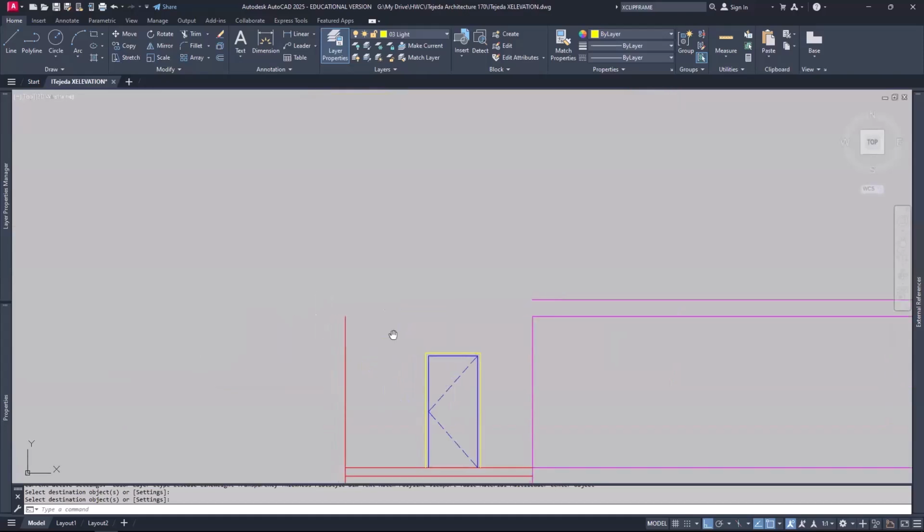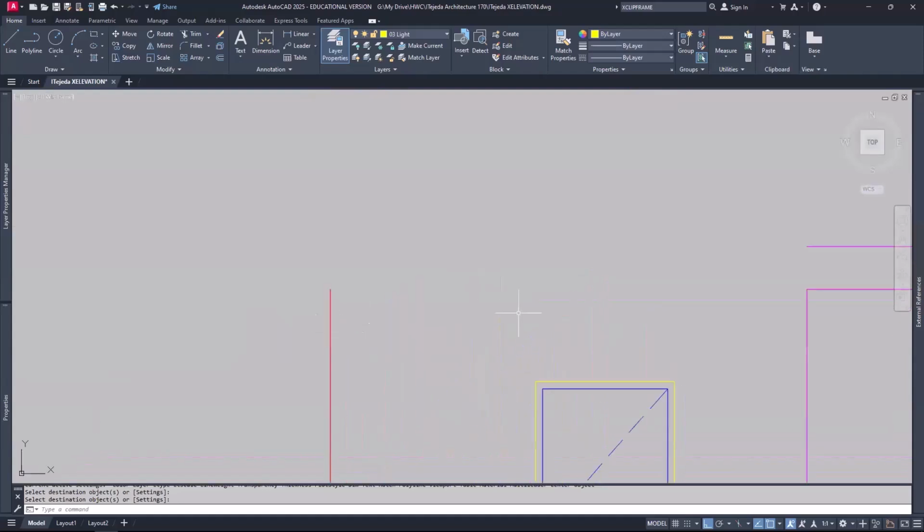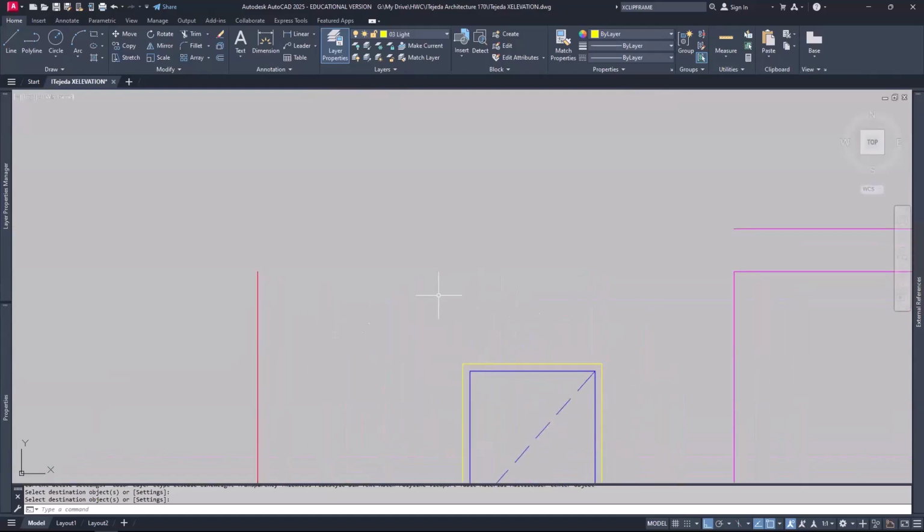All right. Over here, I'll do the same thing. And I like to zoom in so I can focus on just that area that I'm going to be editing. So I'll type L, enter. I'll pause right here and track over a total of 1 foot, enter, take it up. And the distance I want to take it up, I'll just track from this endpoint, bring it over, lock it in right there, and enter.